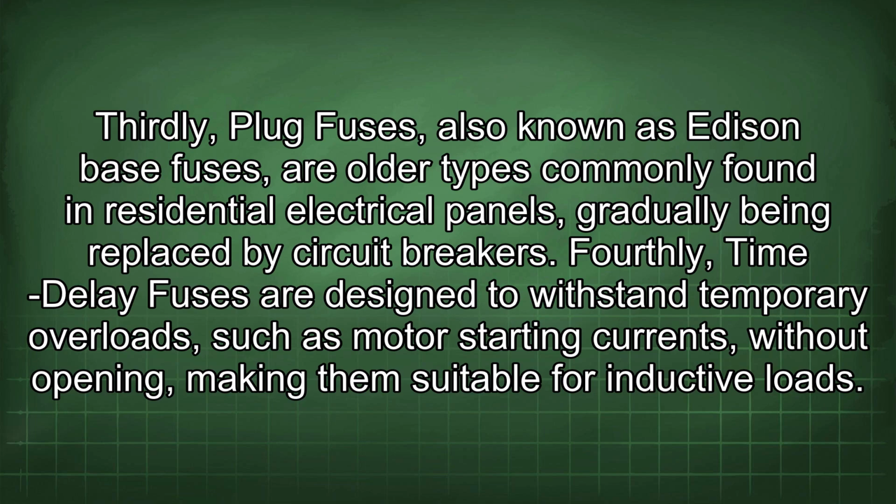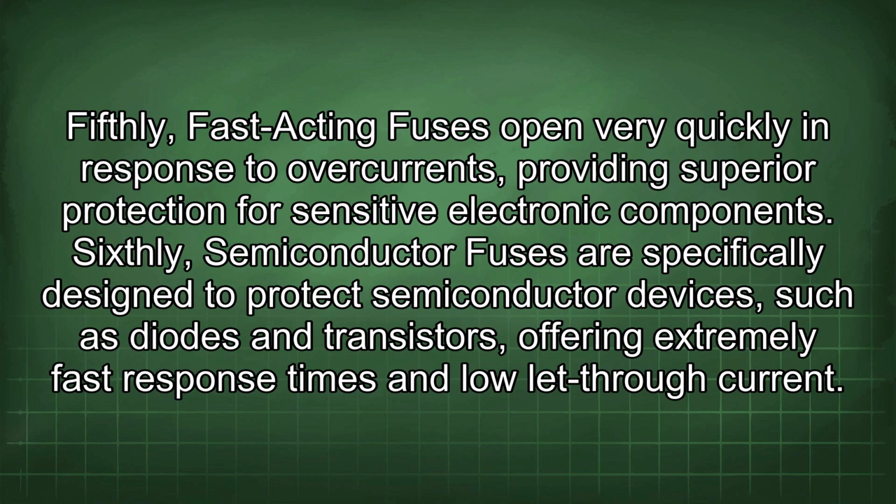Fourthly, time delay fuses are designed to withstand temporary overloads, such as motor starting currents, without opening, making them suitable for inductive loads. Fifthly, fast-acting fuses open very quickly in response to overcurrents, providing superior protection for sensitive electronic components. Sixthly, semiconductor fuses are specifically designed to protect semiconductor devices, such as diodes and transistors, offering extremely fast response times